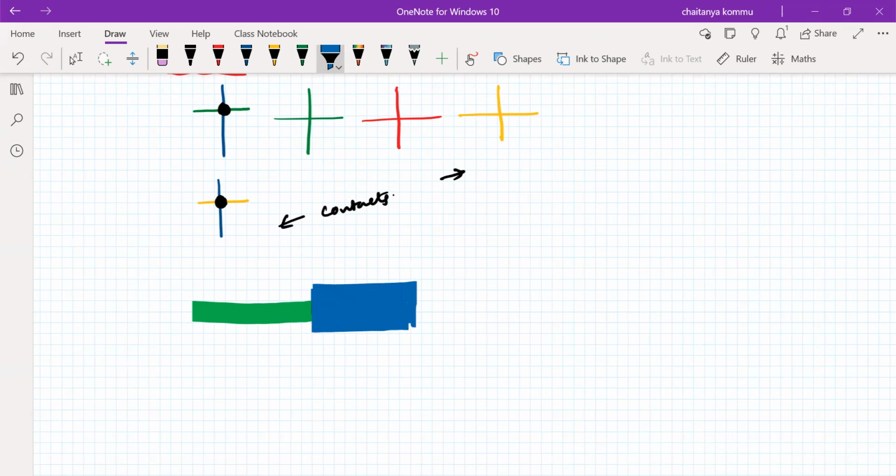Minimum 3 lambda we have to maintain, right? This is the 2 lambda, this is maintained 4 lambda. So therefore, a contact cut is required here. Therefore, what I have to do is take the overlap region of 4 lambda by 4 lambda. I have to take the contact region of 4 lambda by 4 lambda.